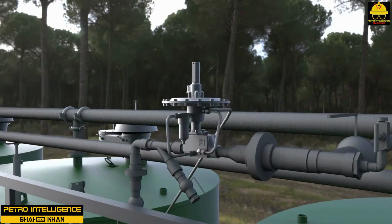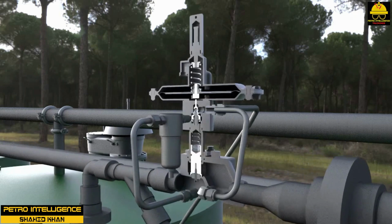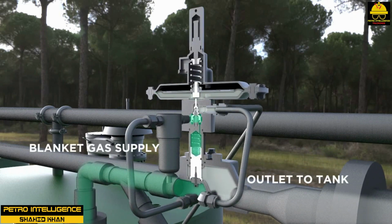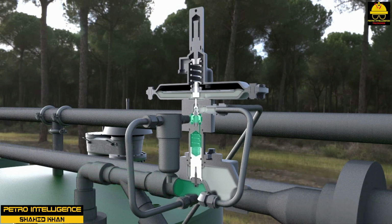They are also used for other stocks when contact with air or moisture would be harmful to the product. In general, gas-blanketed tanks are similar to other types of fixed-roof tanks except that they are equipped with a supply line for the gas blanket and a regulator to control the pressure.